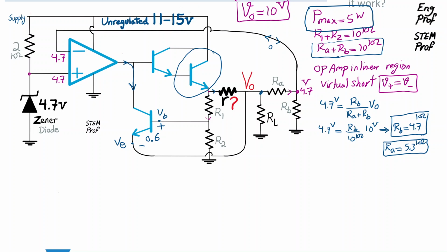So here we have 15 volt, and at the output Vout, let's find the value of voltage here, and then the value of voltage here, and then from there figure out what's going on. The voltage drop across R for the maximum current in the circuit is going to be negligible. So from the perspective of power consumption for this transistor, we make the assumption that we talk about Vout at, say, 10 volt.